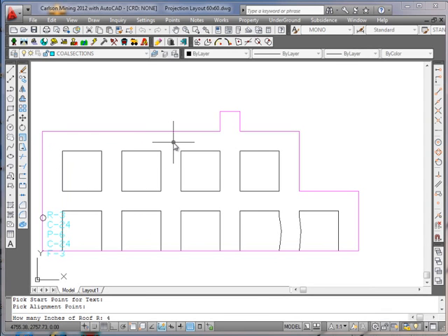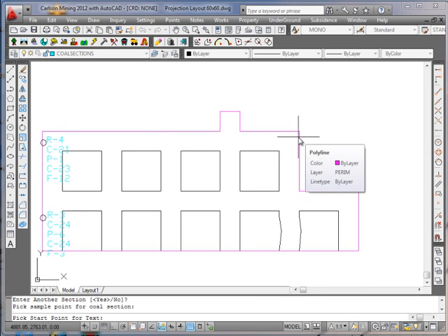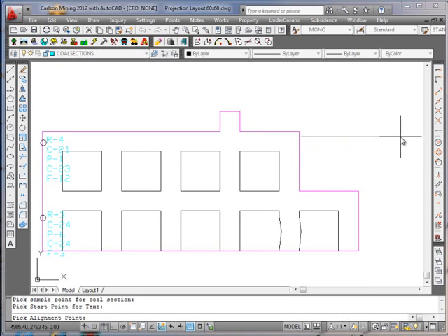So then again we'll come through with so much for the roof, 21 for the upper split, 1 for the parting, 23 for the lower, 12 for the floor, and we'll do another one, and we'll come over this side, pick here, and we'll set the text just to the outside, and we'll say there's 6 inches of roof, 30 inches of coal, 3 inches of parting, 25 inches of coal, and 2 inches of floor.